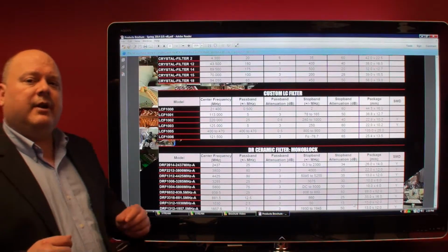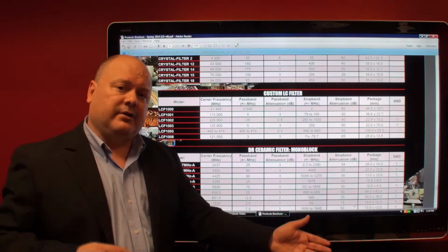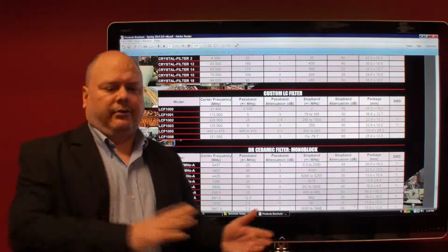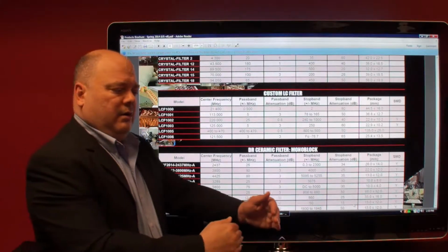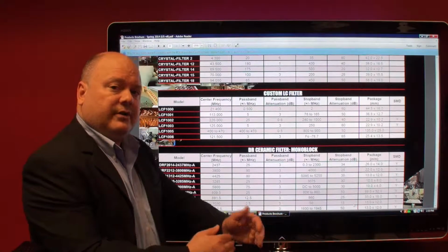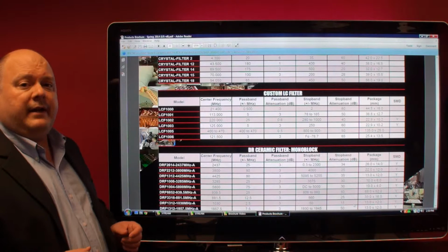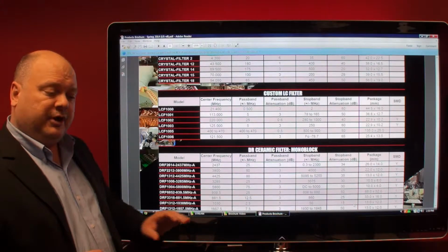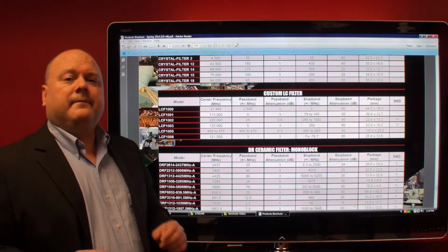The most common frequency range, for example for military radios, is 30 megahertz to 88 megahertz or 30 megahertz to 512 megahertz, all with different center frequencies, all the different LC sections in a very large package filter bank assembly, where the switching electronics is on the underside of the board, software controlled.